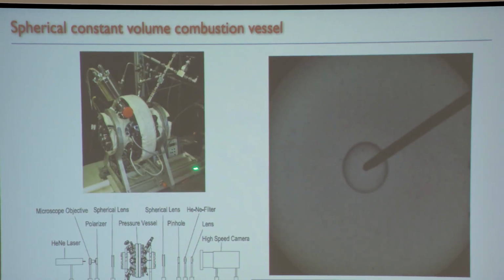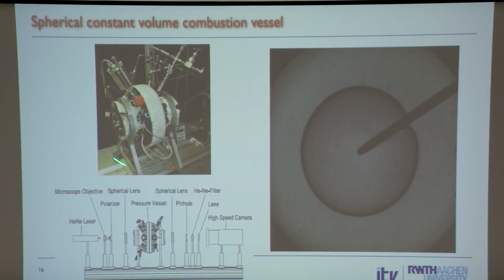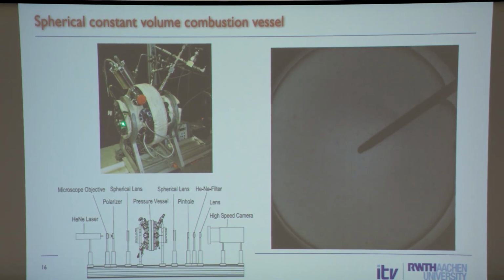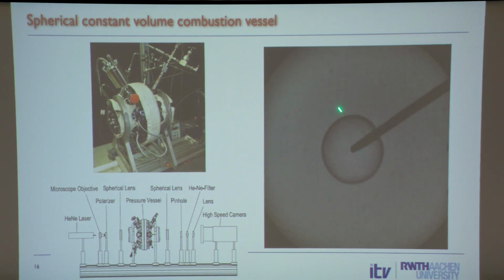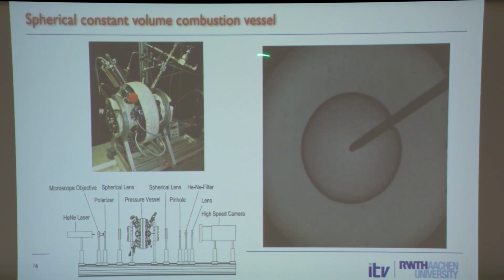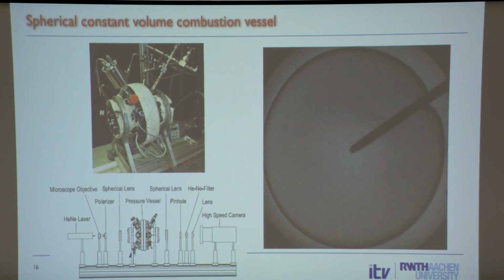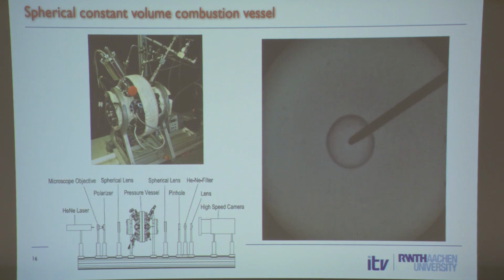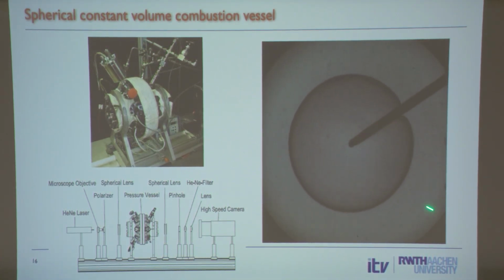This is a chamber that we run in our lab. Usually, there's a lot of insulation material around this also, but you see here the windows on the left and right side. Here's a schematic. Here you have a little window, and then this is the electrode. You have 2 electrodes that come from one side and spark in the center, and then you see from the Schlieren image how this propagates.